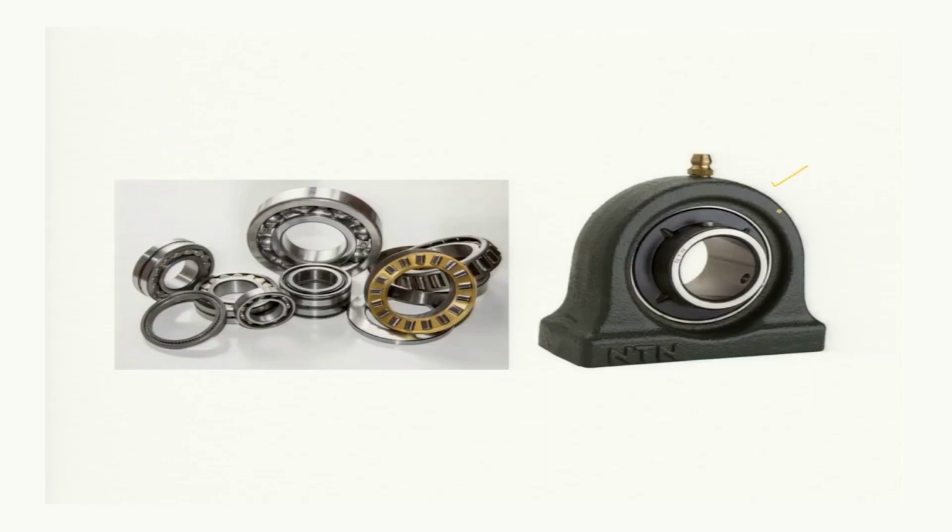So you see, this is your journal bearing or the sliding element bearing. The bearing will look very simple like this, but in the case of rolling elements, we have different components, the inner race, outer race, the ball and the cage, like that, and in the disassembled part the roller is visible here.